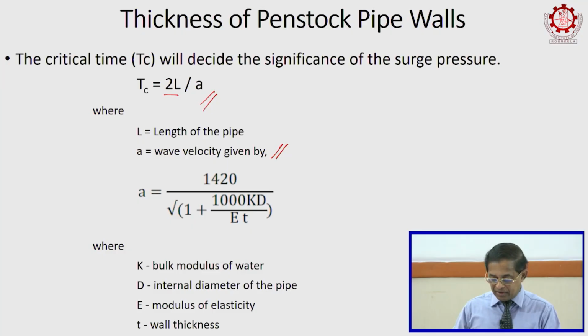To calculate that time, you can use this formula. This is again from hydraulic books. The various terms are there, and I have given the bulk modulus of water. Do not worry about these things. You can get them from handbooks, and then you only have to worry about the units. You have to put compatible units, otherwise they will not match.